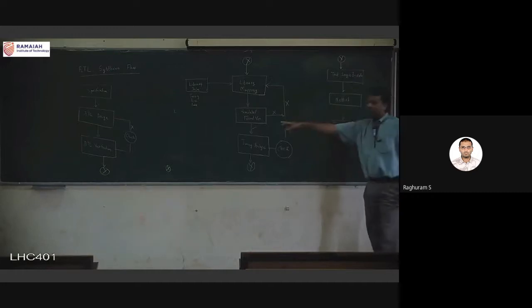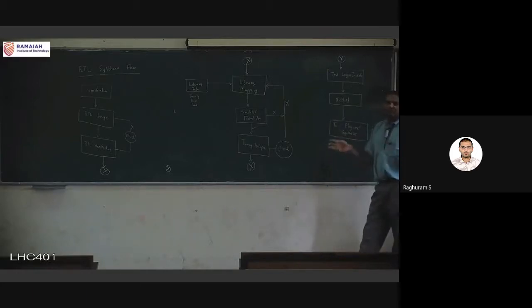And generally, we don't do simulation after this because, like I said, that's a different mode of operation. Test and normal mode will never mix. Okay, suppose you're buying an IC today, you cannot put it in test mode because before it's given to you, that pin will be disabled. They will not remove all this. It's impossible to remove it.